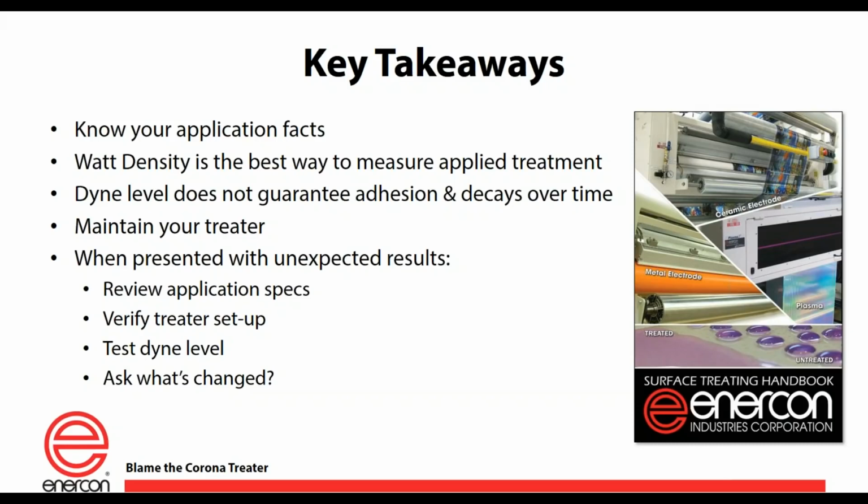Additionally, dyne level doesn't guarantee adhesion, and as you guys know, it does decay over time. So when you're buying film from some other place, you can certainly expect that as that film ages and things change with it as it's sitting in storage, that dyne level is going to be different than maybe what you expect. So as we know from our friends at Acme, it's really important to test the dyne level of the film prior to you putting it up on the line.